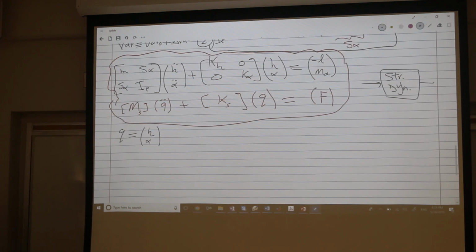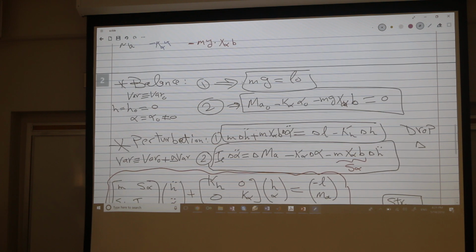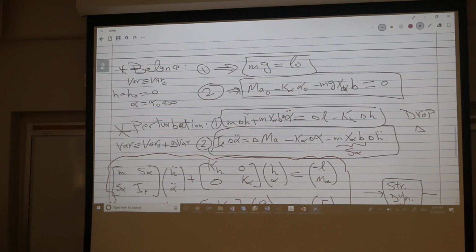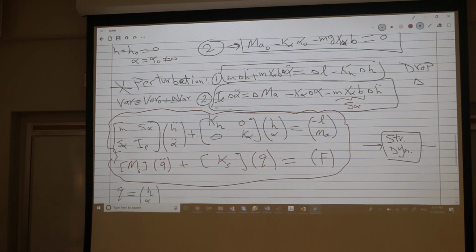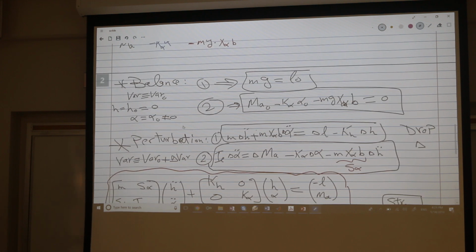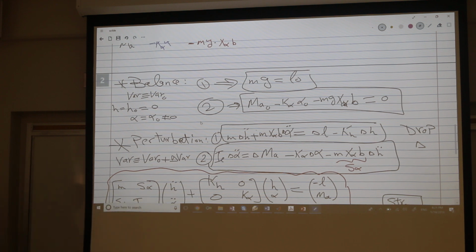Yes, Lee? Is the process of finding the equilibrium and then the perturbation the same as the linearization? Exactly. I'm looking for a linearization. The resulting model is a linear model. Yes. Basically, I'm studying the linear stability. Even if you have a nonlinear system, I would say more than 90% of the time, the linear stability analysis is sufficient. And it's very straightforward. You have a linear model, study its stability like I'm going to show in a minute. Sometimes the linear stability analysis is not sufficient and you need to do nonlinear analysis. This is very few cases.